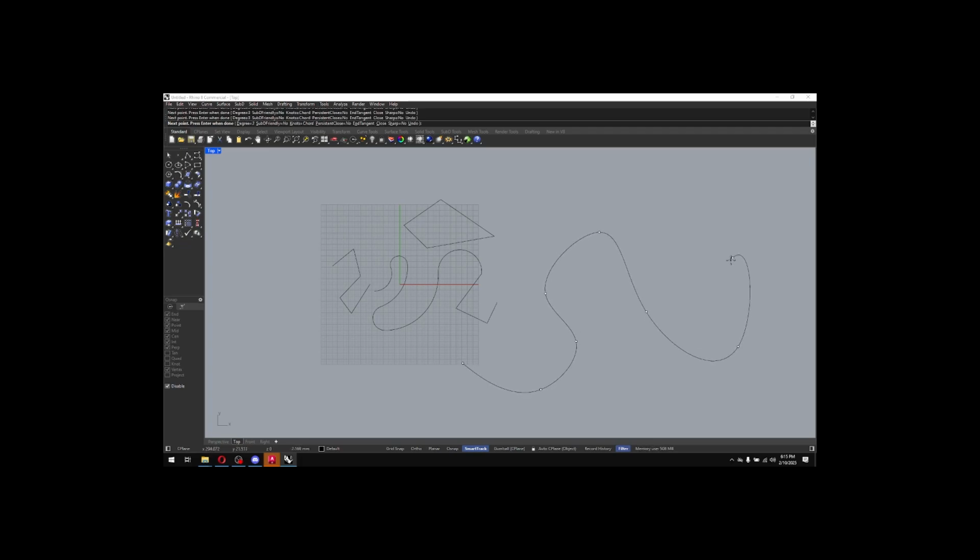So you can make some really nice organic shapes, things like that. You can't build off of splines, so I suggest when you're putting construction sets together, never use splines ever. Always use arcs and things like that, because you can actually build off of it. But if you're just making something nice looking and you want it to have a little bit of a graphic nature to it, splines can look really nice.